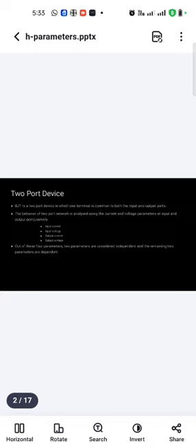The biasing resistors and transistor are coupled through the coupling capacitor. Using the coupling capacitor, the input signal or source voltage and series resistor are connected at the input. Through the coupling capacitor the load resistor is also connected, and across the emitter resistor we use a bypass capacitor. We name that bypass capacitor the CE capacitor. This is the introduction to BJT amplifiers.